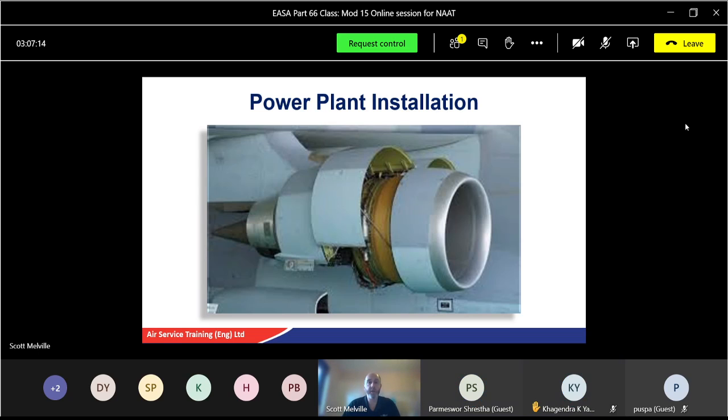Normally, if everything's working fine, it stays where it is. If it's gotten hotter, something has escaped from the HP side. So maybe a turbine casing cracking, or a hot air pipe within the HP side is now letting hot air escape to where it shouldn't be going. So we've got a problem somewhere. Don't think too deep, just think we've got hot air from the HP side.